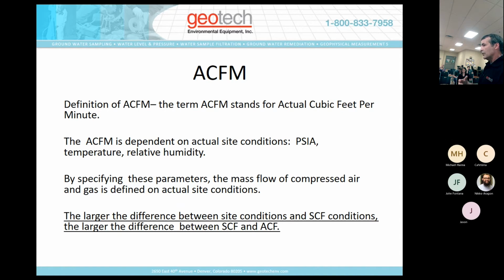For instance, a blower that's doing 50 CFM at 50 inches of water in New England at sea level will not do it at elevation in Denver. You have roughly a 15 to 20% reduction in the blower efficiency based on elevation. So we would have to upsize the blower to get that 50 CFM at 50 inches of vacuum.